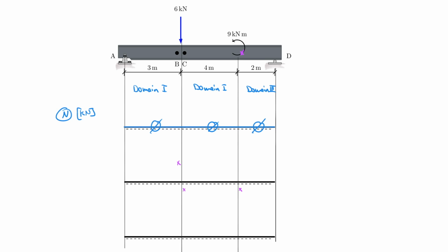Now, can I extrapolate my understanding from previous problems and from what I've learned as I set up the equations? Yes, I can. So what influences the shear force distribution from here to here is really only the support reaction, and remember that was actually 5. So really how I should draw my diagram would be up with 5, because that's my RAY. So this is RAY,